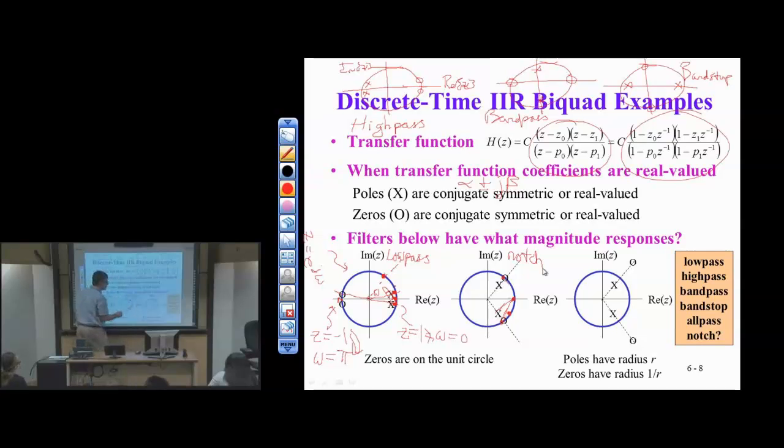So in terms of magnitude of response of the notch filter, right, so this is a notch, and this is the magnitude of response. So there's your notch filter. And this notch frequency is what? What is this? Where's this? What frequency is being eliminated? It's the angle right here. So there's omega naught. That's omega naught. Now here it happens to be pi over 4.